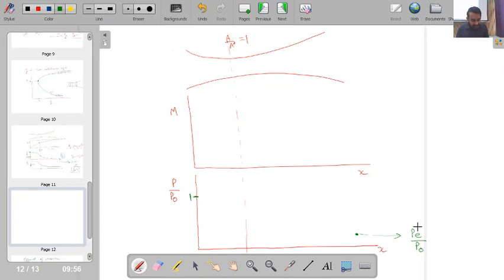Okay. Now say in place of choosing PE, I have chosen a very small pressure difference across the inlet and outlet. So I have this PE1 by P0 over here, and this PE1 is selected in such a way that P by P0 at the inlet and outlet are very, very close. So I have chosen a very small pressure difference. If I choose a very small pressure difference, then what will be happening? I will be having some flow in the nozzle, but flow velocity will be very, very low.